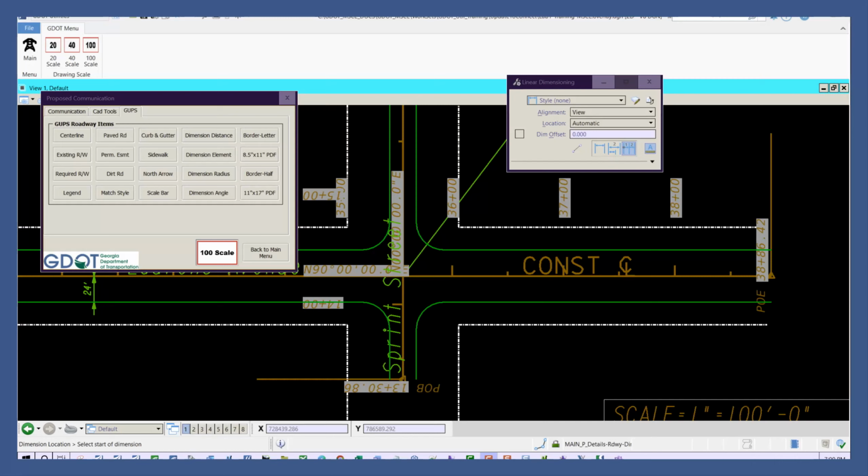To revisit the angular dimensioning tool, this tool has angle size, location, between lines, arc size, and arc location modes. The prompts in the lower left corner of the MicroStation Connect Edition dialog will be contingent upon the mode selected. The intersect snap and other snap tools can be used as needed to aid in the dimensioning process.